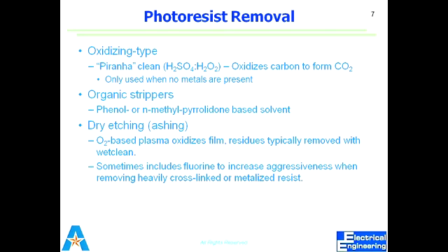In this case, dry etching, because it's actually a gas, has more access to deeper trenches. And secondly, wet etching is mostly isotropic. Isotropic means that it etches vertically and laterally with the same etch rate, but dry etching etches in one direction. Even wet etching can be anisotropic, but when you discuss etching, you will come to know about that.